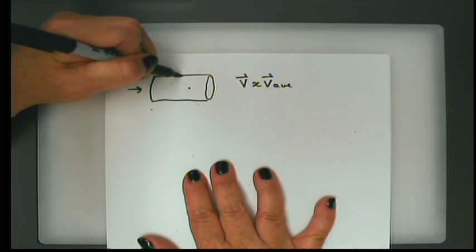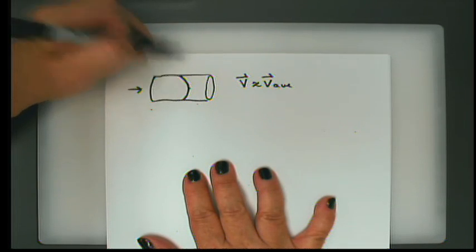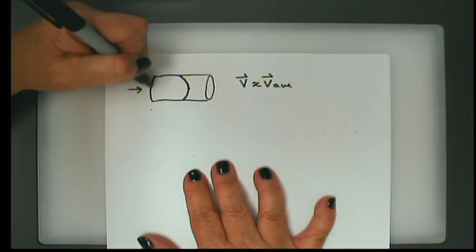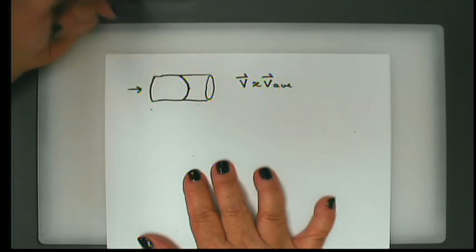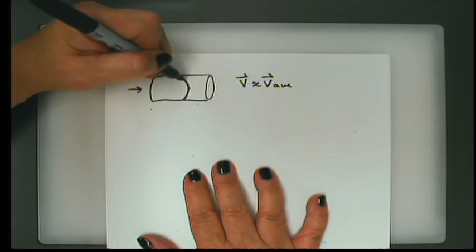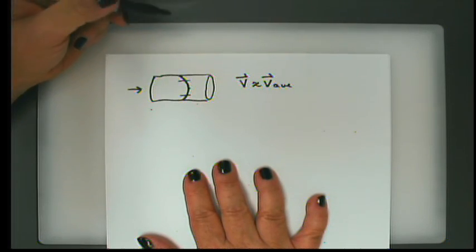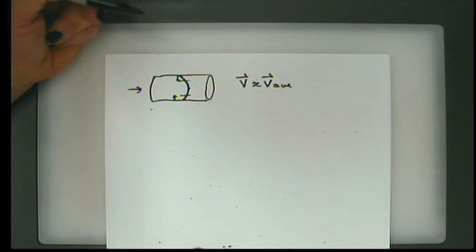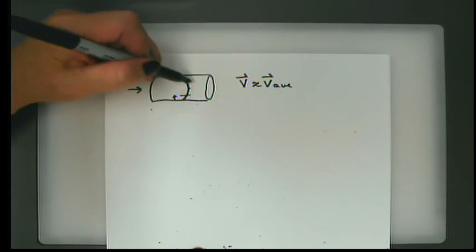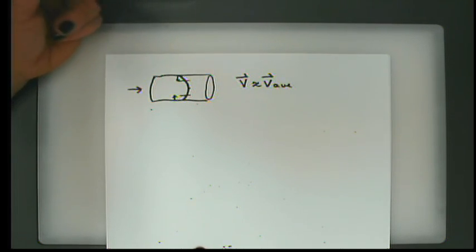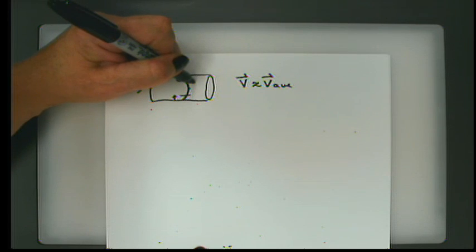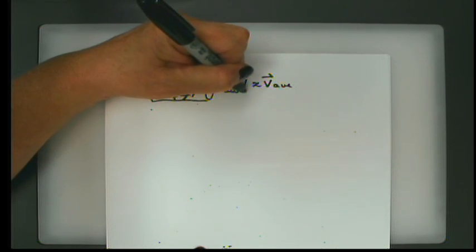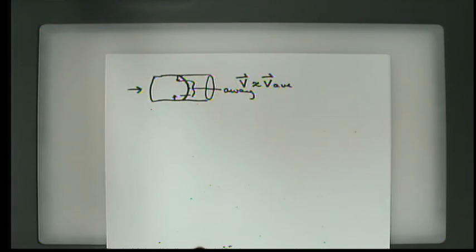And what tends to happen is you get a nosing out or parabolic shape of fluid movement. So if you started with a flat profile of fluid here, it will nose out as it goes through this tube. At the walls, near the walls, and we'll have to quantify later what near means, the viscous effects are very important. But toward the center of the tube, it's often the case that the viscosity is not important, and that we actually can approximate the fluid flow in that region as inviscid.